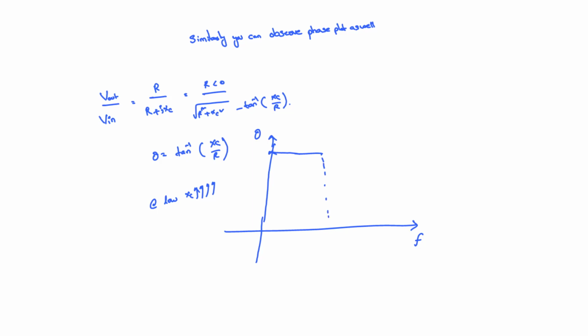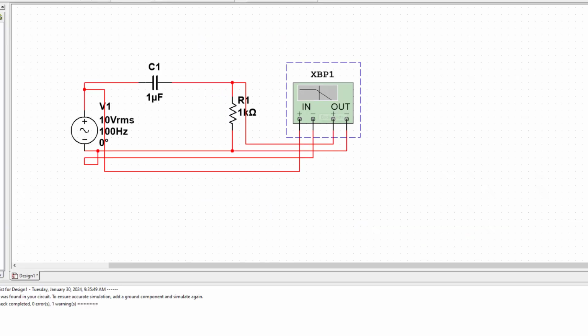Now here also we need to observe at what particular phase angle this is getting changed. That particular phase angle is called the critical angle, which in this case is 45 degrees. So let us observe from the simulation, from the Multisim perspective, what the 45-degree point is and why it has so much significance. This 45-degree point should be the 3 dB point. It indicates in what way the signal is moving, whether it is going the amplification way or the attenuation way.